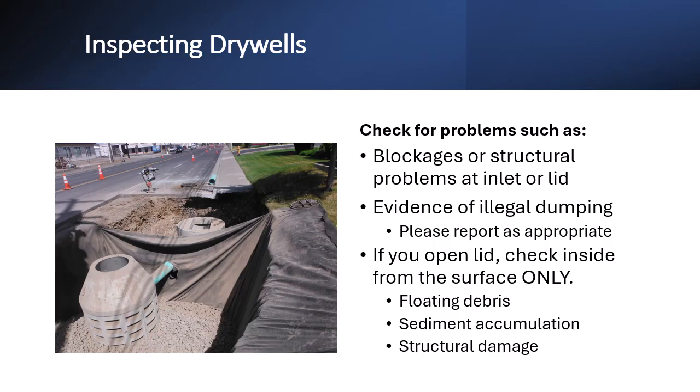From the surface, you can check for the following: floating debris, sediment accumulating above the first row of slots from the bottom, or structural damage to the drywell.